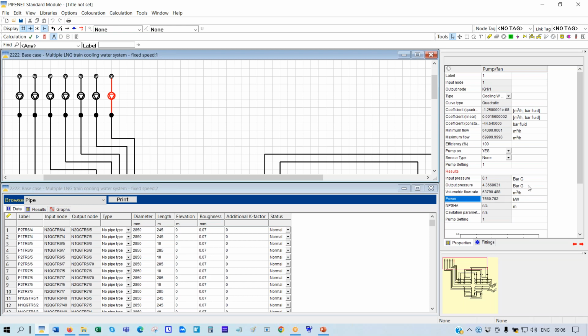And cooling water pumps normally have a low delta P, and that's why you can use fiberglass pipes, because the discharge pressure is not very high. So if you trim the flow rate, you can change a huge amount of power, and that you can see here.